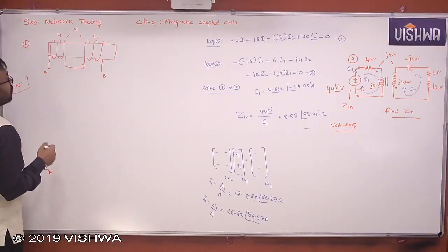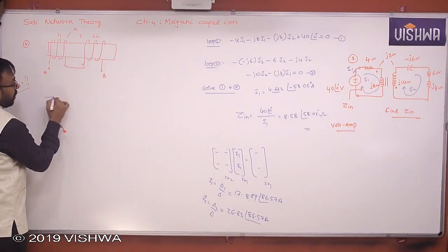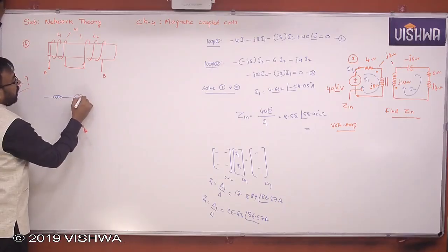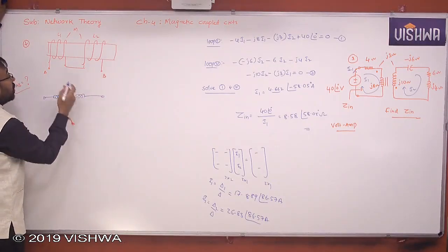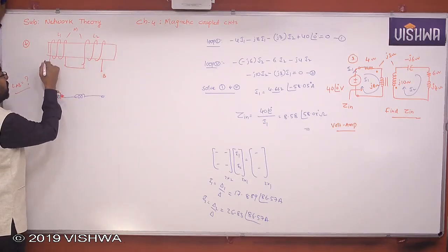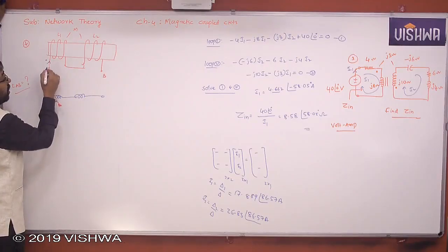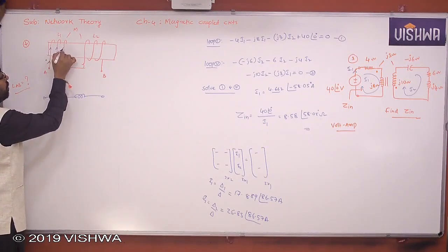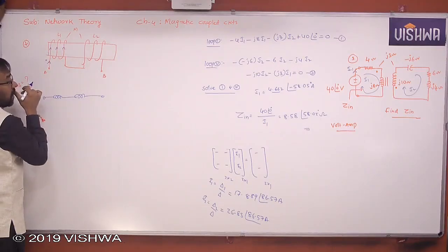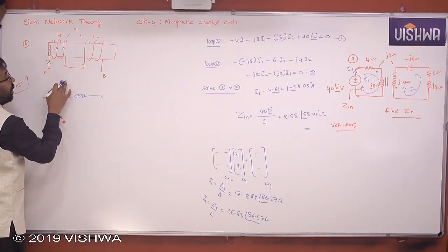Okay, so we need to actually indicate the inductors like this, but dots are very important. For dots, you know how to find. First, you identify one coil. Identify the terminal where the current enters. Yes, I identified here with an assumption some current entering. The current is flowing like this. According to Ampere's law, some flux is produced. Flux links with this particular coil. Faraday's law of electromagnetic induction says that EMF is also induced in it.